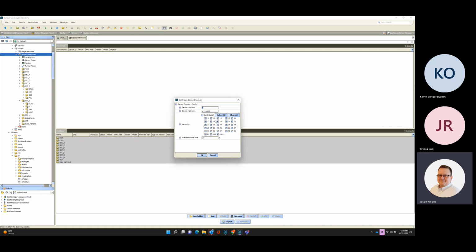Now, let's say you tried to take 3 of these networks, MSTP wires, and pull them to a physical JACE that was just in sector G. And I'm talking G, first, second, third floor. Can you imagine how slow that would be? Can you imagine how long it would take to get the data to the graphics if we did the antiquated MSTP protocol?